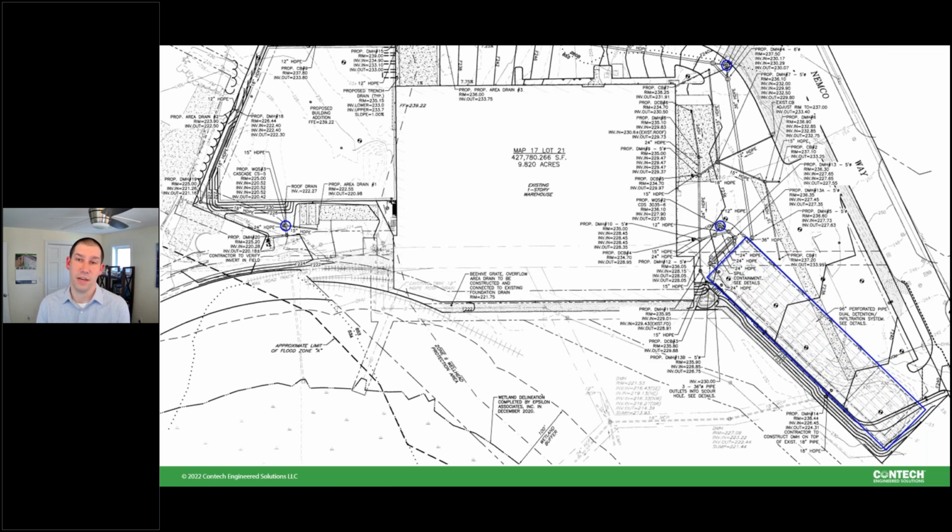So when you're looking at this final site plan here, you can see the existing building, and the new building in the upper left, that was the whole pond before. Everything from that side, as I mentioned, now comes down to this detention system. And you can see the little blue circles there. Those were Cascade or CDS units being used for pretreatment.